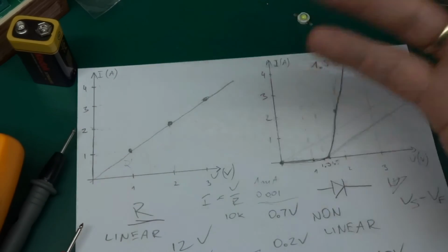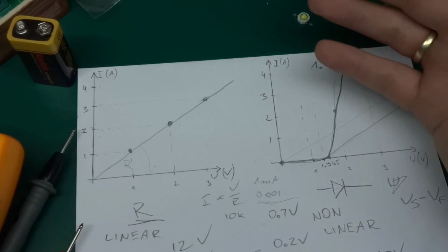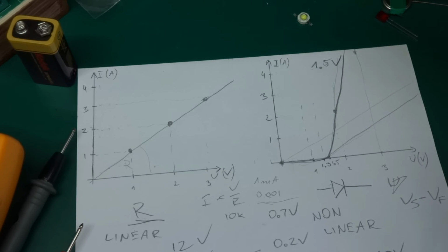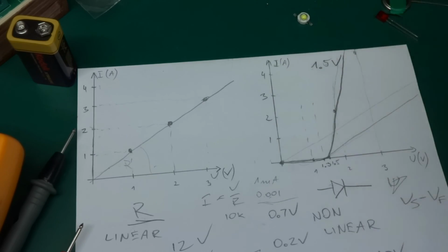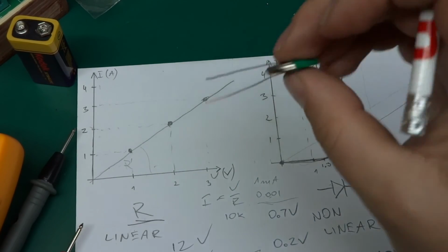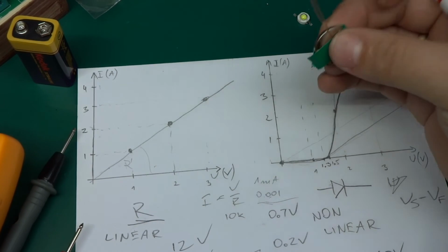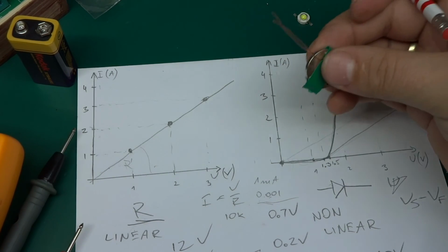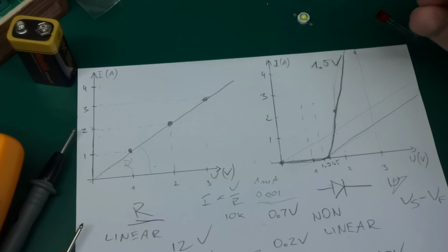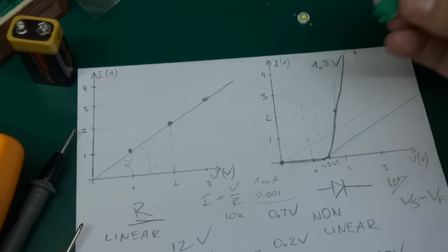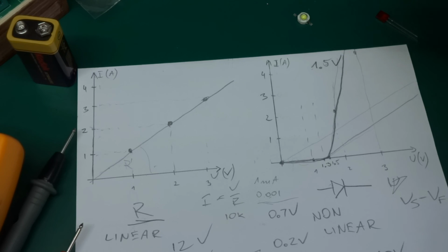If you use a multimeter on ohms range, you're expecting an LED to actually show something, but it doesn't, and you think it's busted. Well, try with something else. Quick and dirty trick: a button cell battery. It will tell you if it's working. No, it won't tell you what the forward voltage of it is, but if it lights up, you know it's working. So if you're trying to troubleshoot a broken product, go look somewhere else, because this part is clearly operational. Maybe there is a broken track, maybe the driver IC is busted, not too sure.